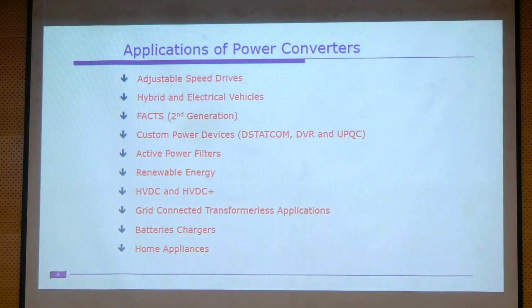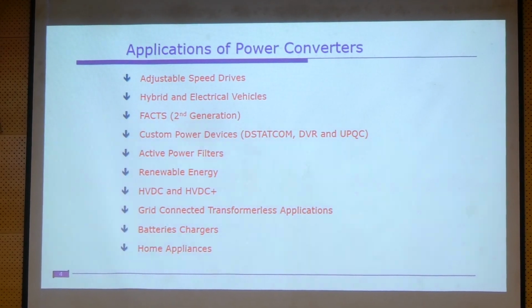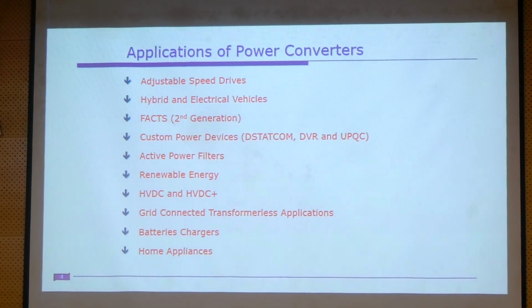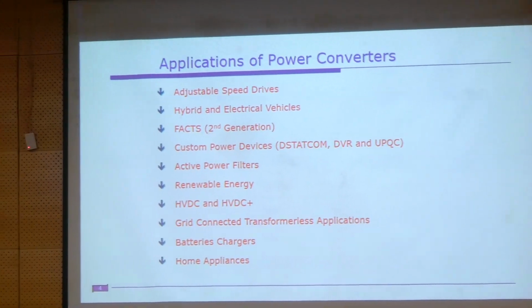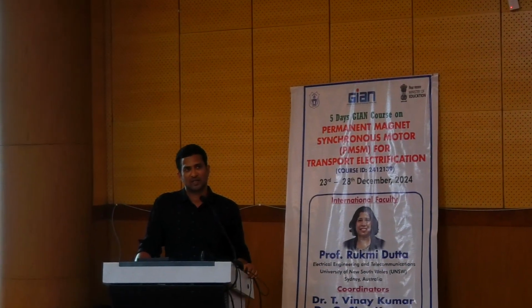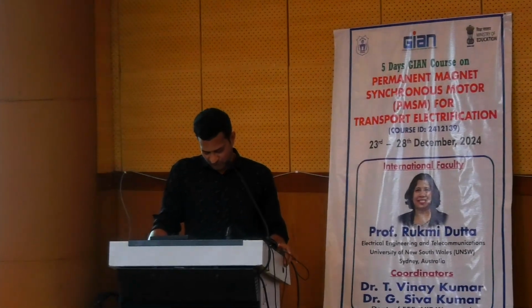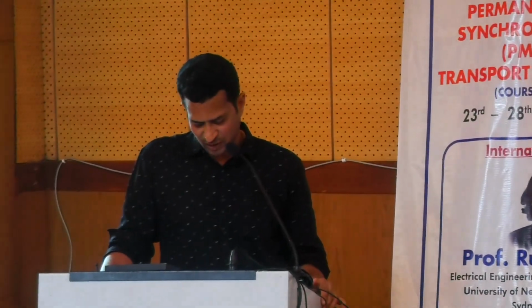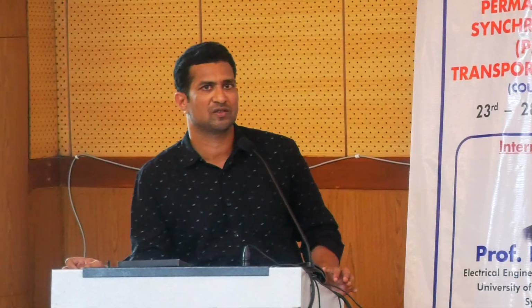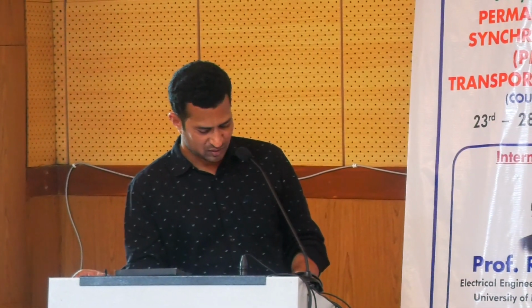Next is HVDC and HVDC Plus. HVDC is converter based, which uses the GTO as the device, whereas HVDC Plus uses modular multi-level converters for direct connection to the transmission lines. Next are grid connected transformer-less applications. By using these inverters, we can connect directly to the main grid.